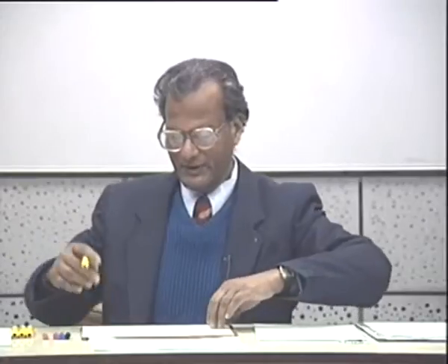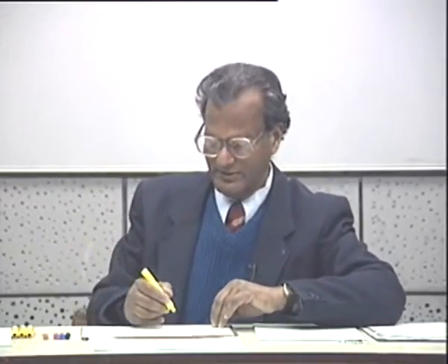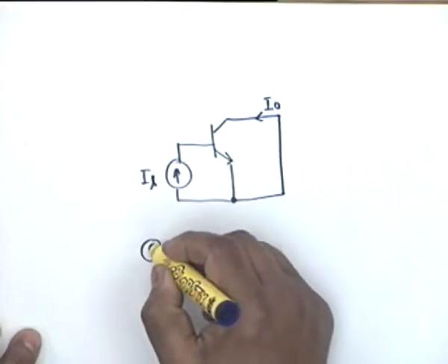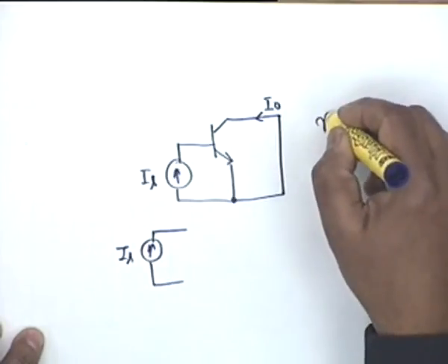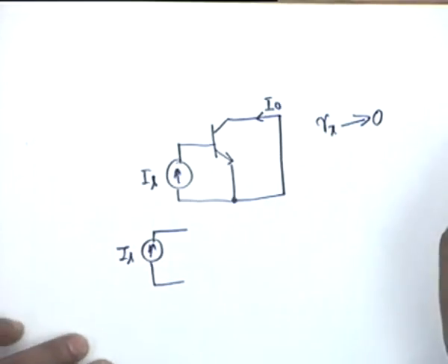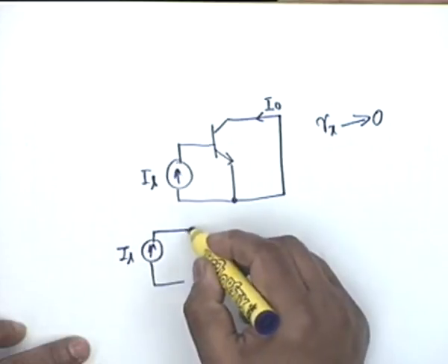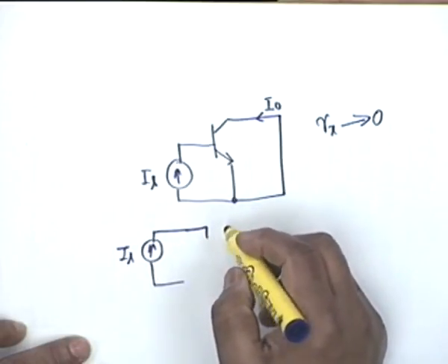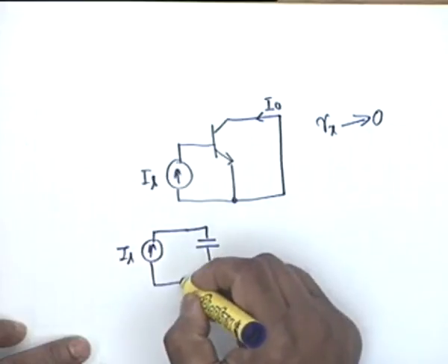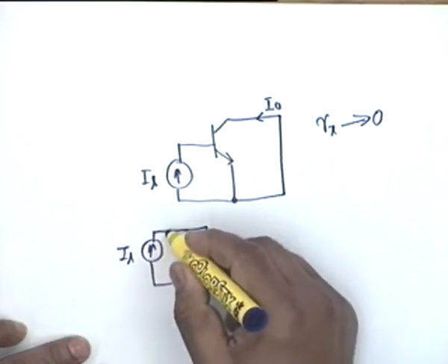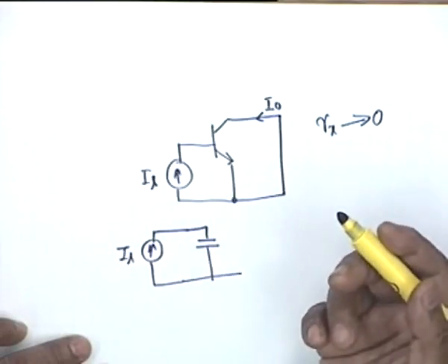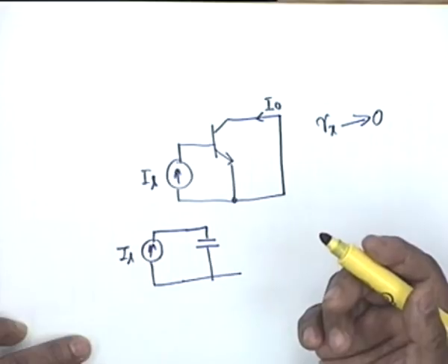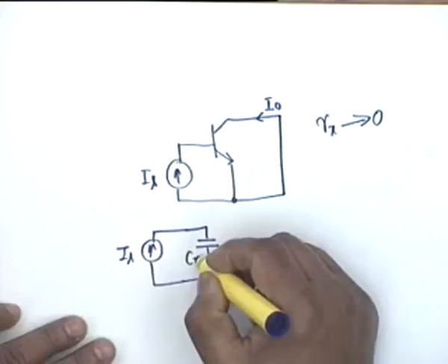Now, if I draw the AC equivalent circuit, what we have is Is. Then it is very convenient to ignore Rx. We ignore Rx; wherever necessary we shall include it, but at the present time it does not add much. It is in series with a current generator, isn't that right? Even if Rx was there, it does not have any effect, because the internal impedance of a current generator is infinity, and Rx plus infinity is also equal to infinity. So it really does not matter.